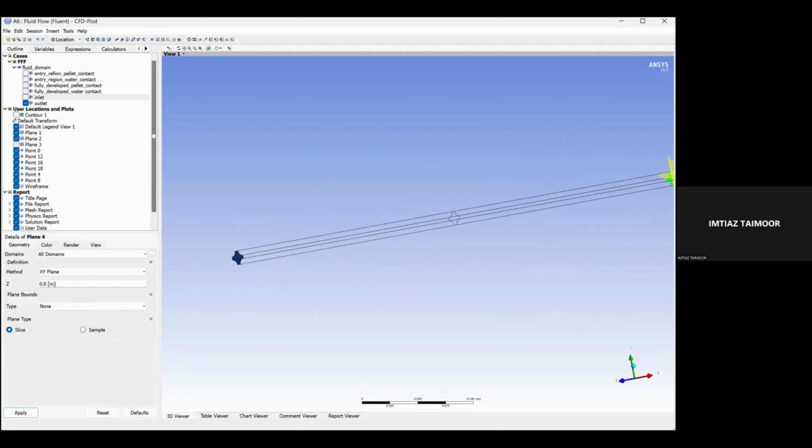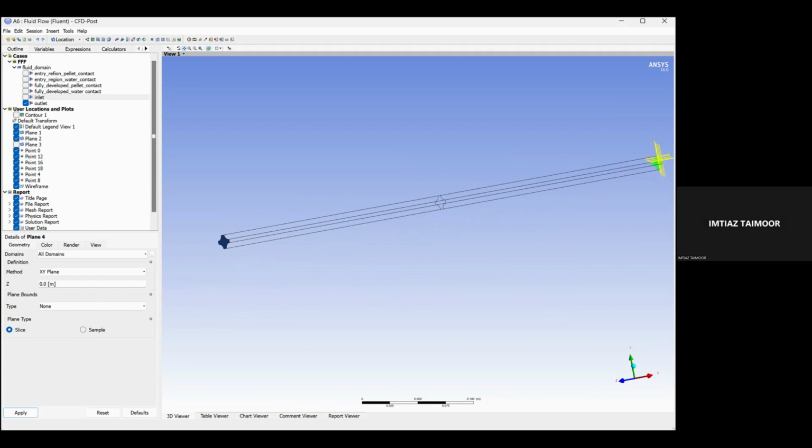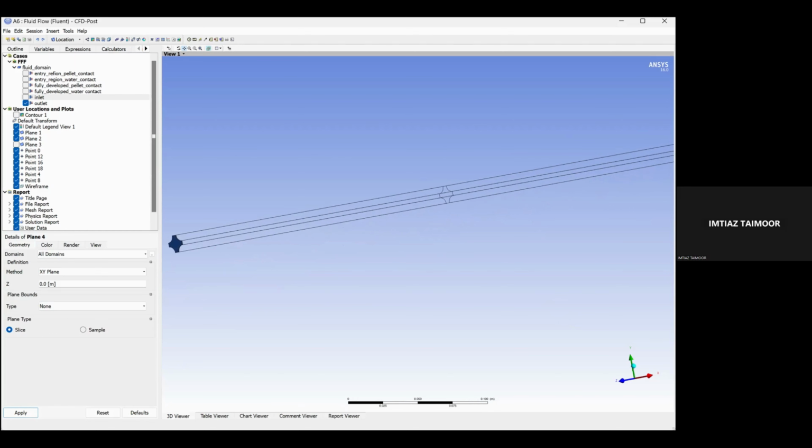In the velocity profile, do you know the D shape velocity profile, the capital D shape velocity profile of a fully developed flow? Do you know that? Does anyone have any idea about that? Yes, sir. Okay. So we want to see that here in this ANSYS. So we will select a plane.